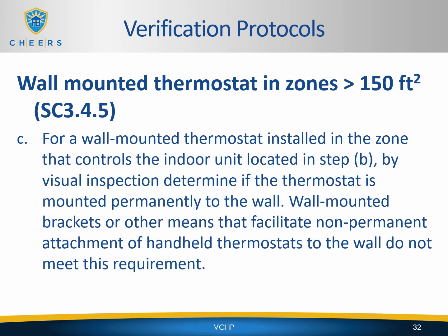For a wall-mounted thermostat installed in the zone that controls the indoor unit located in step B, by visual inspection determine if the thermostat is mounted permanently to the wall. Wall-mounted brackets or other means that facilitate non-permanent attachment of handheld thermostats to the wall do not meet this requirement.